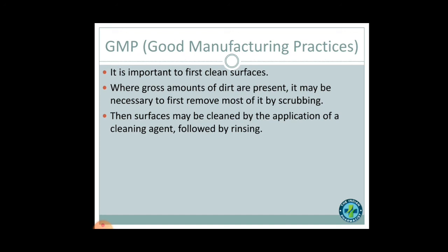Hard bristles, like steel bristles, should not be used as they may leave metal pieces in the product, which can cause harm to the patient and contaminate the product. Then surfaces may be cleaned by the application of a cleaning agent followed by rinsing. This rinsing will ensure that the cleaning agent has been removed from the surface.